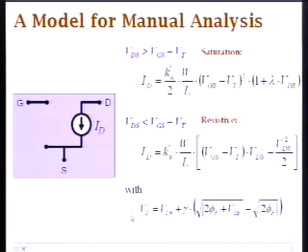So we basically look at the transistor as a 4-terminal device. Gate voltage controls the amount of current that you can produce with your transistor. Then the drain to source voltage controls the mode of operation. You have either linear or you have saturation mode. And then finally the bulk potential, and that's what you're going to be doing in your homework, modulates these characteristics. So it's going to shift them up and down depending if you do forward or reverse body bias. But this is a set of equations that you need to be really familiar with.